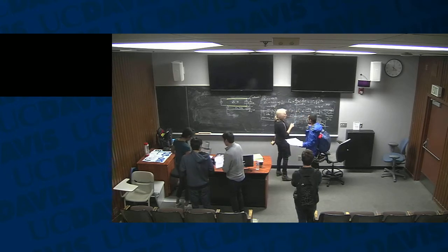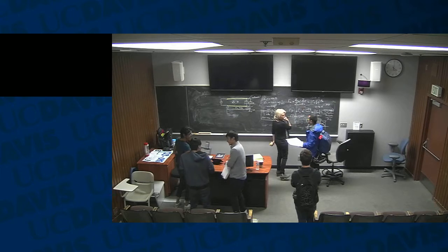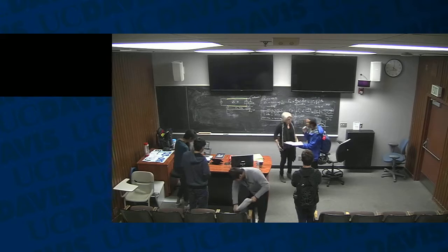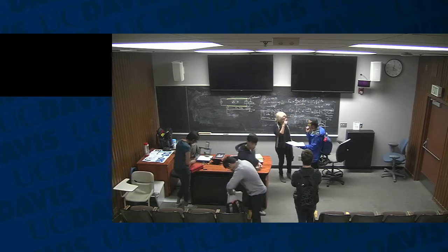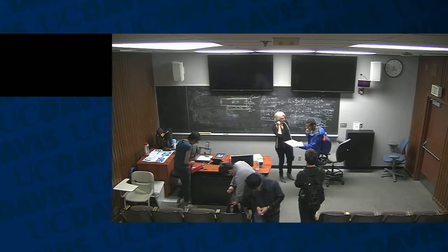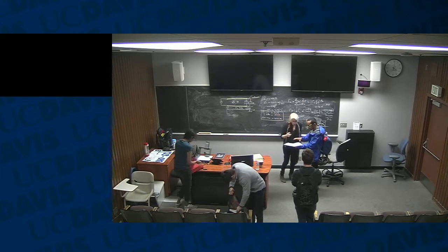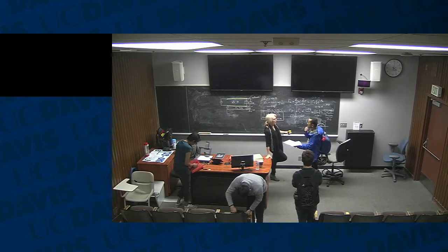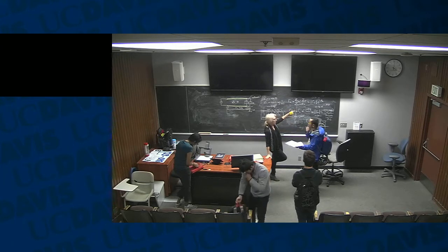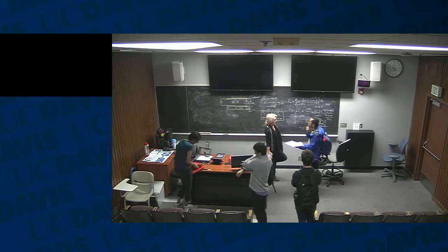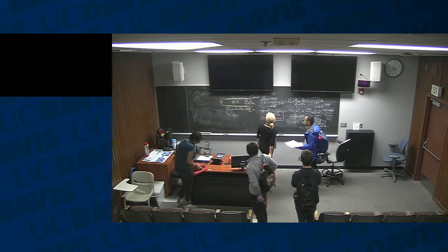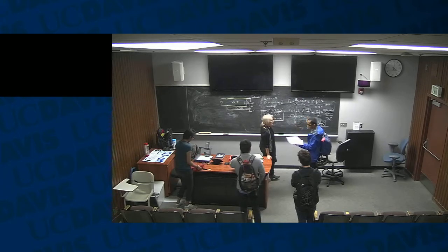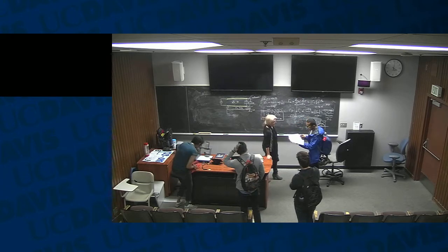Because I'm going to give you beta, and I'm going to give you Z naught. To see that the Z naught can be calculated out of R, L and C, which gave us this lossless result. Because I may give you L and C and say find Z naught. I may not give you Z naught explicitly, but I may give you the R and the L and C of the line. So that derivation helped us show that there's a relation between L and C and beta, and how we can work interchangeably with that.